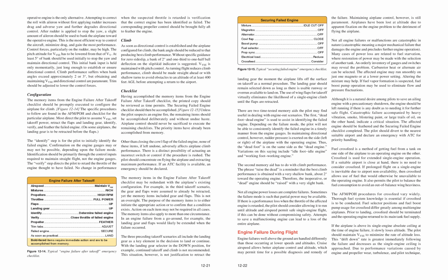The 3 preceding takeoff scenarios all include the landing gear as a key element in the decision to land or continue. With the landing gear selector in the down position, for example, continued takeoff and climb is not recommended. This situation, however, is not justification to retract the gear.